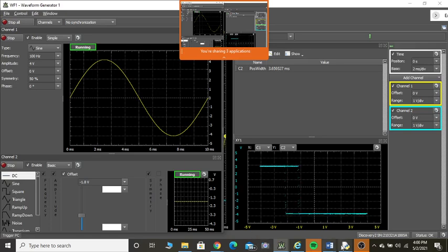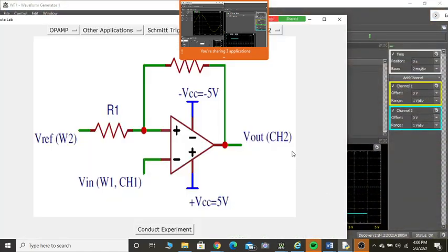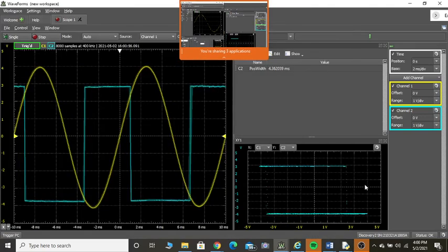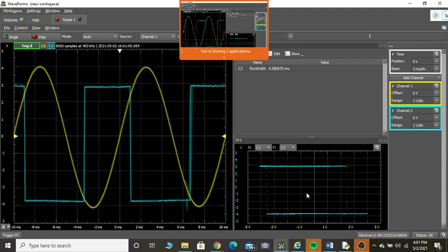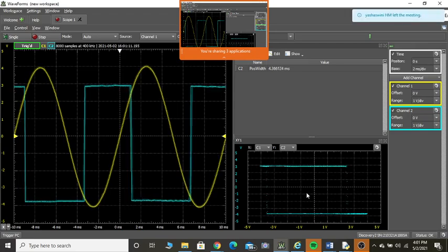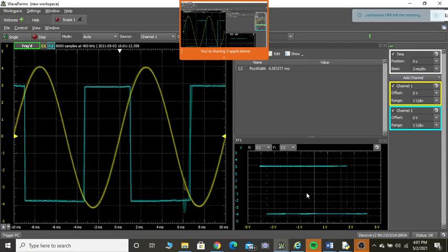If you change R1, R2 to a different combination, now let me select a third combination and then start conducting. Can you see the width has increased too much? Can you see now the hysteresis width is too much? So can you differentiate between the first, second, and the third? So there you are changing R1, R2. So that's why naturally the hysteresis width is changing.